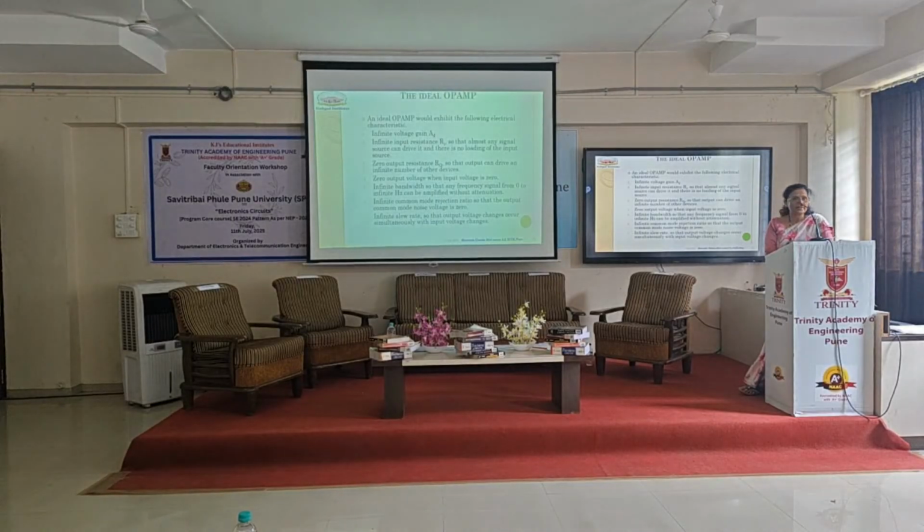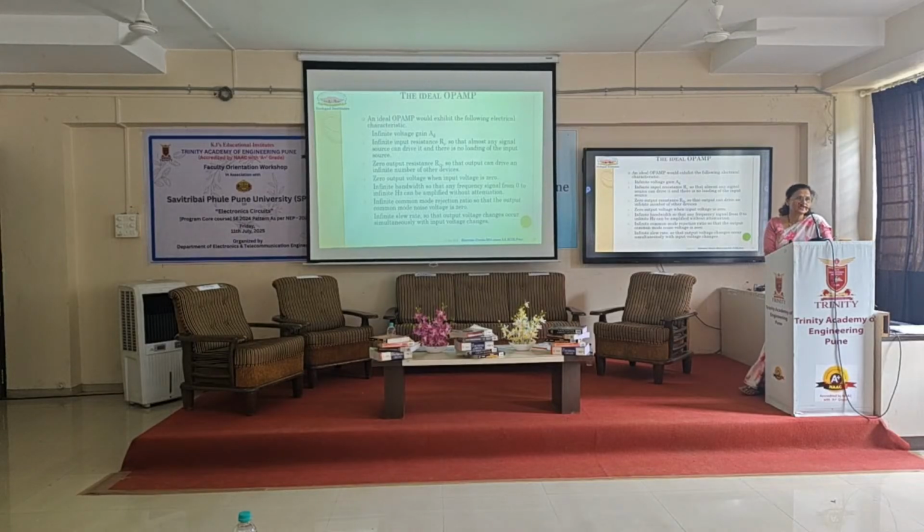These are some ideal characteristics of the operational amplifier, similar to the discrete amplifier, whatever we learn using discrete components. If we are expecting that circuit should have maximum input resistance, minimum output resistance, and high voltage gain and current gain. No doubt, along with these four parameters, operational amplifier has some additional features like slew rate, CMRR, along with the offset voltage and offset current.